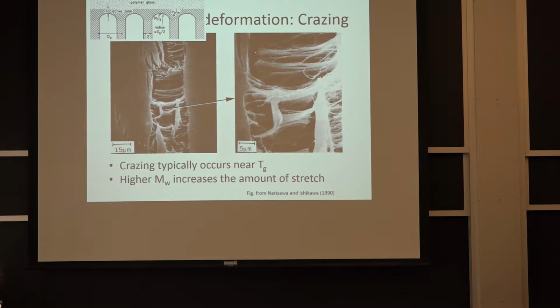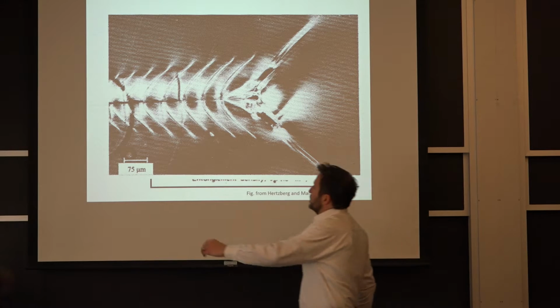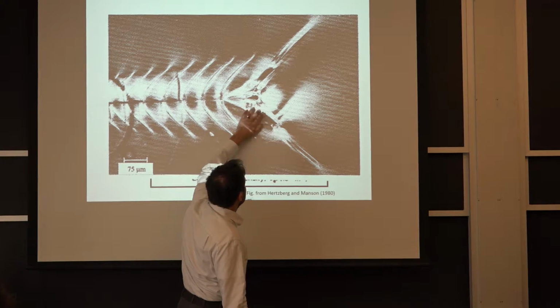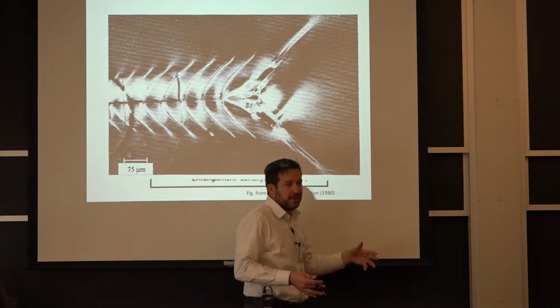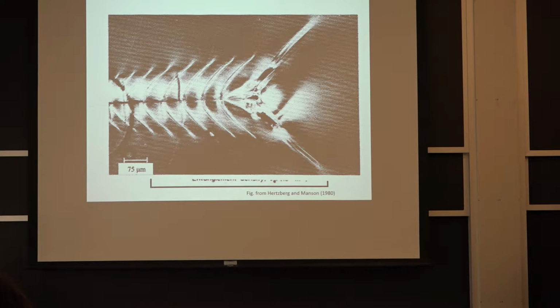It's not to say that when you have an amorphous polymer, you can't have some special deformation that either facilitates or stops the crack. So the reason for that image, if you remember from last week, is I was mentioning why polycarbonate is very tough, because with the crack going this way, and because you have these shear bands forming on each side of the crack, you really are blunting it more, and therefore you increase your toughness, your resistance to cracking, by that ability of polycarbonate to deform.